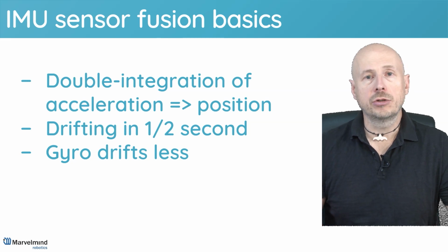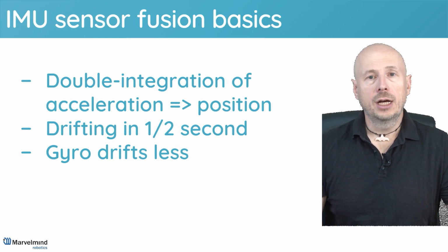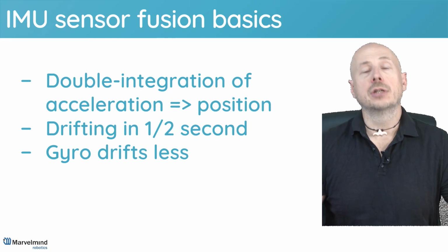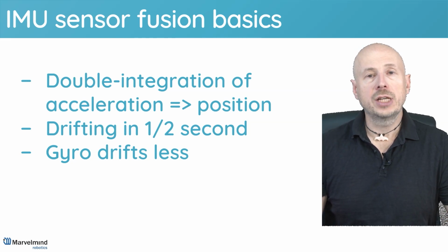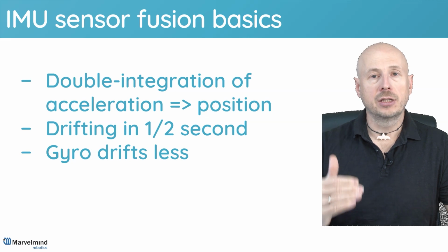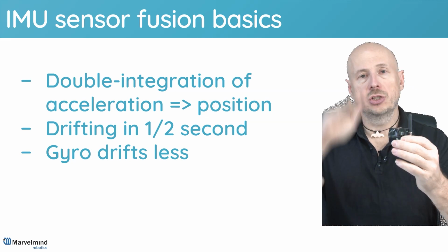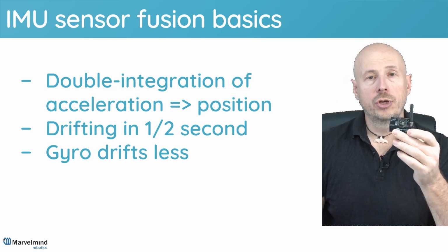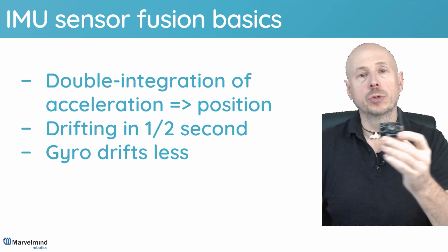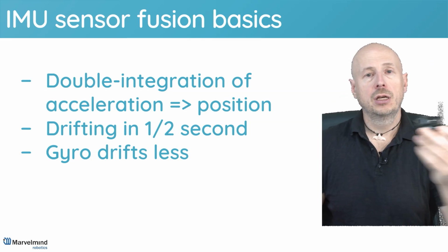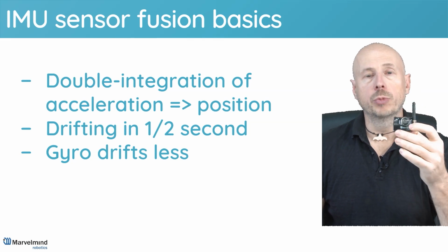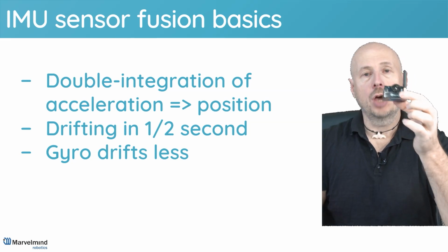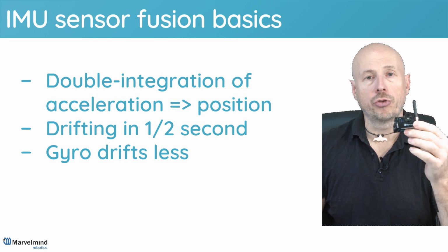But low drift with zero gravity. When you have non-zero gravity, and obviously when we are on Earth, it's very difficult to subtract a huge acceleration that gives the Earth from the acceleration from the movement. For example, if you are just moving like this, you have nearly zero acceleration of your own movements. And at the same time, you have 1g acceleration to the Earth.